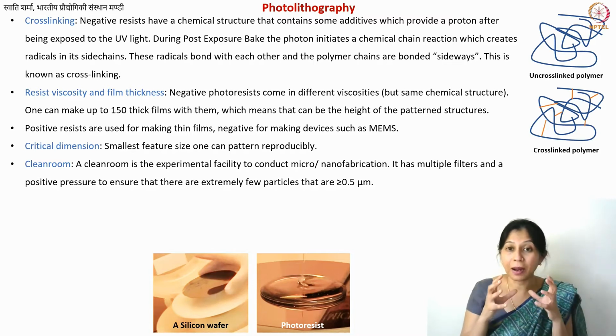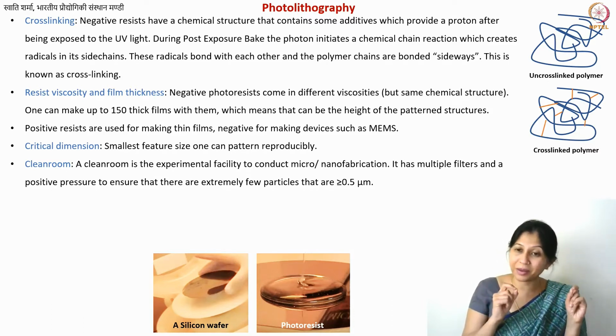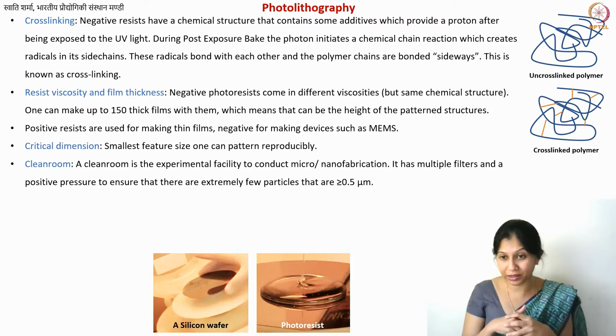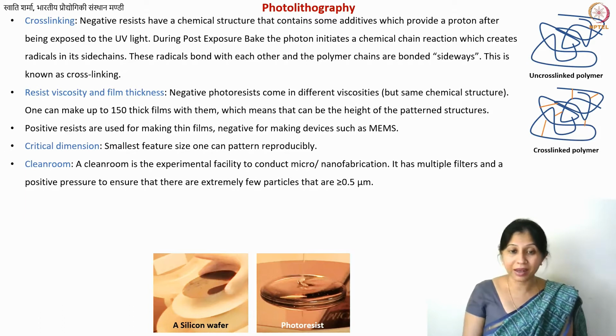This is a facility which contains multiple filters, and it ensures that the number of particles larger than 0.5 micrometer in diameter is minimized. Now, why do we do that? Because what we are making here is only a few micrometers in size. Let's say you had a particle 10 or 20 micrometers in dimension, but the structure that you're making is itself 20 micrometers.